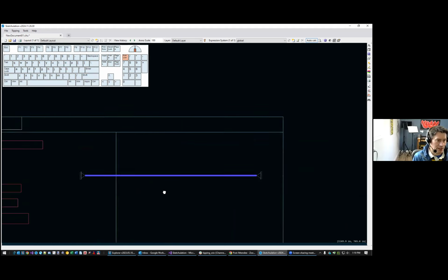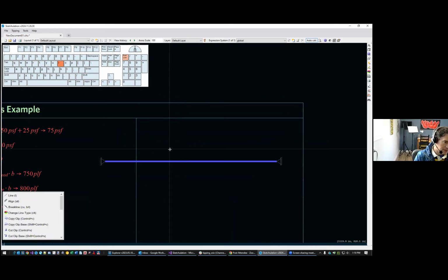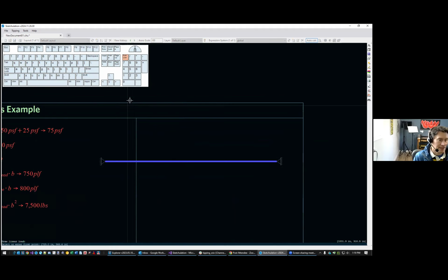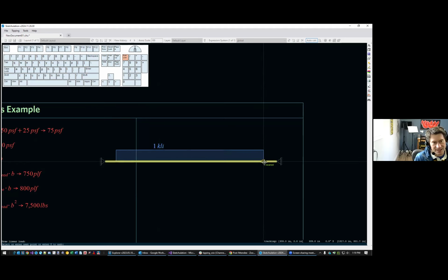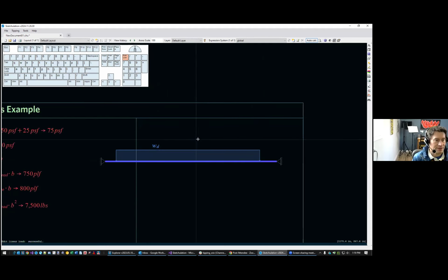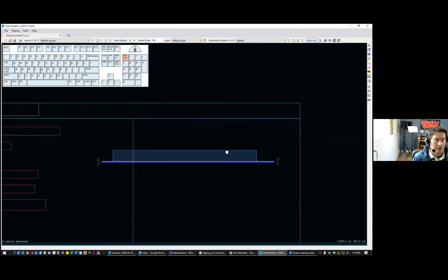So now we're going to draw in our linear loads. You can start to type linear, and you'll see it says load linear, LDL. I have that one burned in my mind. LDL, and now it's asking me to select the points on the beam where this will go. Just for fun, I'm going to not select the full ends. I could snap to the ends, but I'm just going to show that you can do it anywhere along here. I typed F2 to start to edit this thing, and I put in WD. So now it's defined with my dead load.